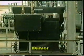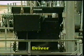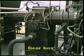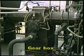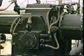The driver is the part of the compressor package that supplies the power to the compressor. It can be an electric motor, a steam turbine, or a gas turbine. A gearbox is often used between the driver and the compressor. This allows the compressor to run at a different speed than the driver. This gearbox may either be a part of the compressor casing or it might be in its own separate housing.